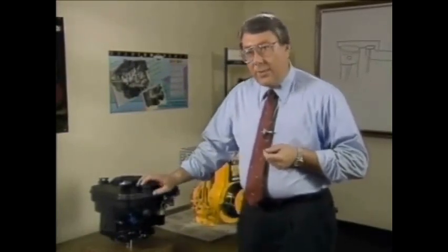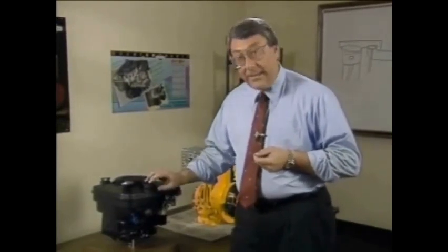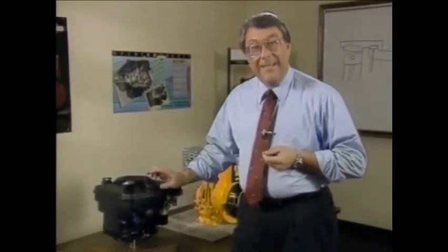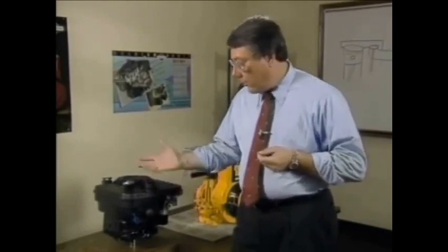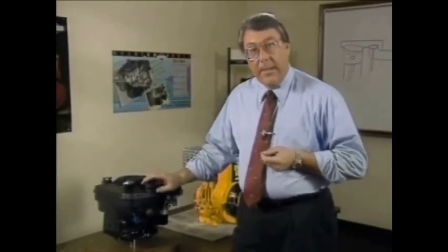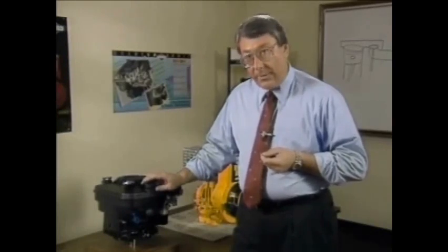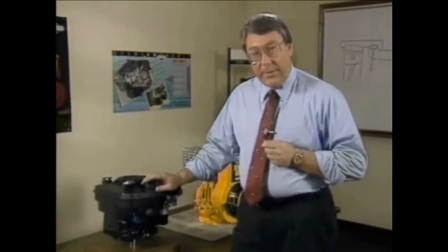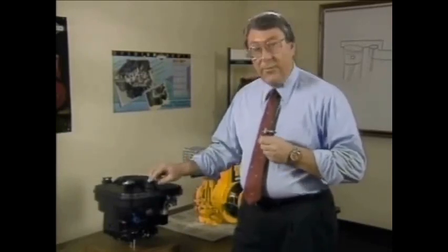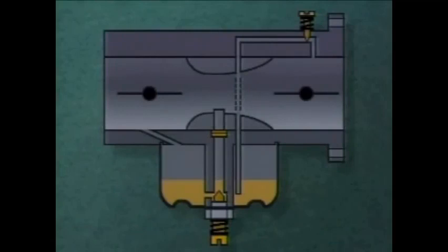You see, contrary to popular belief, gasoline does not burn. Gasoline vapors burn. And the more we can vaporize or atomize the fuel before it enters the combustion chamber, the better and cleaner the engine will run. To do this, we can start by premixing the fuel with air. We'll do that by adding an air bleed to the high-speed pickup tube of our carburetor.